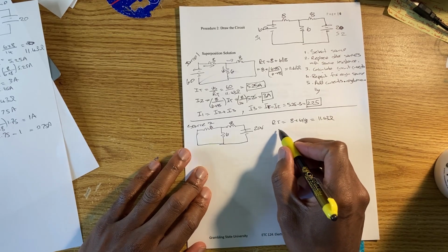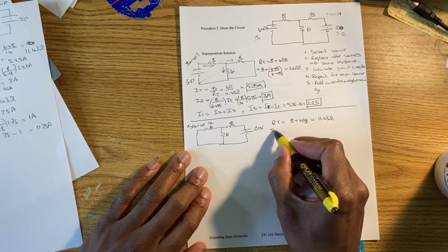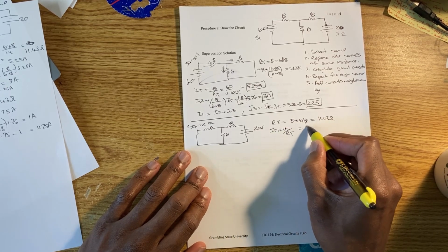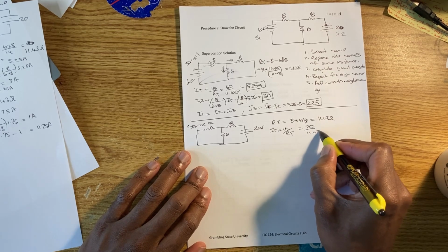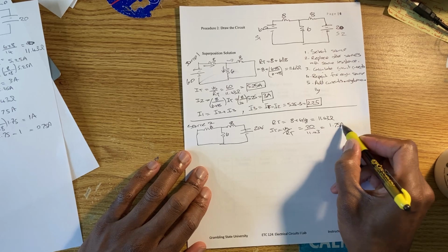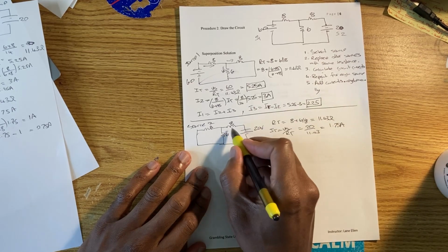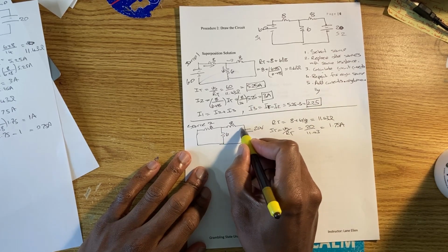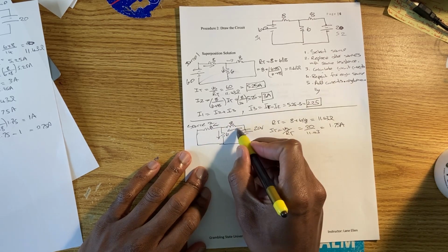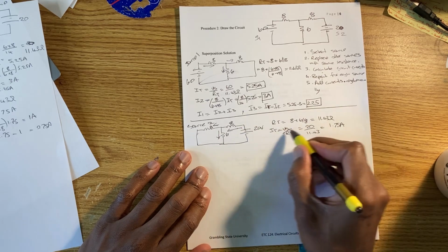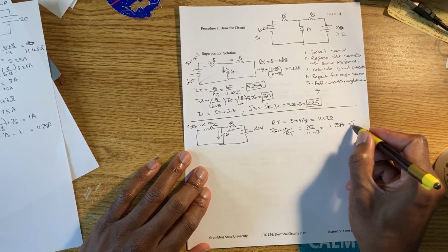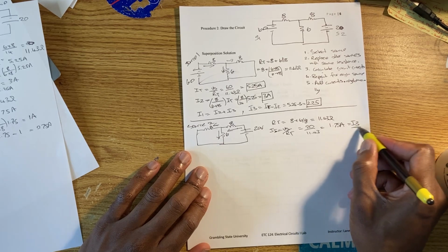Then we can go ahead and calculate IT. IT is Vs over RT, which gives us 20 over 11.43, and that gives us 1.75 amperes for our total current. Now again, what is the direction of the current? We assume our current is coming from the batteries, going this direction. It's going to split up here, right? So our main current now is I3. So this IT that we just calculated here is the same as I3. So I'll just put a note here that this is equal to I3, right?